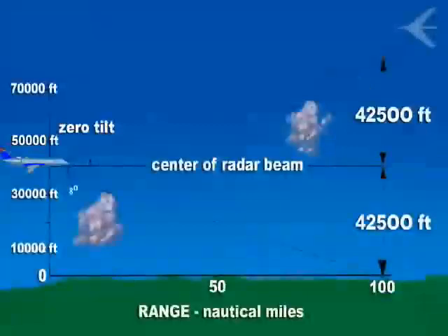There is a recommended tilt adjustment technique in this case. This procedure is not to tilt the radar beam towards the top of the buildup, because this portion is the frozen portion, consisting of snow, hail, and cirrus clouds, but rather to the middle, where the radar can detect liquid water. Check the figures showing the relationship between tilt angle, flight altitude, and selected range.